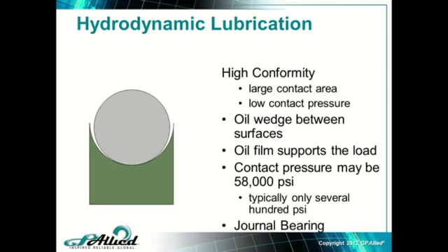Now, as that molecule comes out of the load zone over here, the pressure starts to drop, and as the pressure drops, the hydrocarbon molecule doesn't have as much strength, doesn't push back as hard, and it loses its viscosity back down to its normal state. So the load characteristics change as the shaft turns with respect to a given hydrocarbon molecule. Now, that's where the word dynamic comes from in hydrodynamic. Its characteristics change as it moves in and out of the load zone. Hydro speaks to the fact that it's a fluid, right?